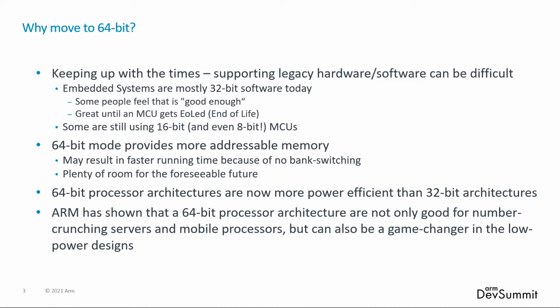and other tricks. In addition, many of the most powerful but still inexpensive processor core architectures are 64 bits today. If you want to take advantage of the highest performance core microarchitectures, you're likely running on a 64-bit ARM core where the newest advances show up first. Things like superscalar execution, hyperthreading, etc., give you more instructions per clock cycle. In addition, the highest execution clock speeds are likely to show up in 64-bit A cores before migrating to embedded